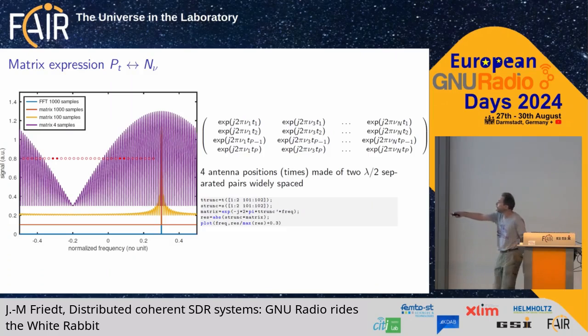And now if you say these two antennas are further apart, which is what you do with VLBI, you say I have two antennas which are not nearby but now further apart. Well, you've got this comb of functions, which gives you the high resolution of the far away VLBI antennas, but because they are far away with missing dots, you've got the envelope.